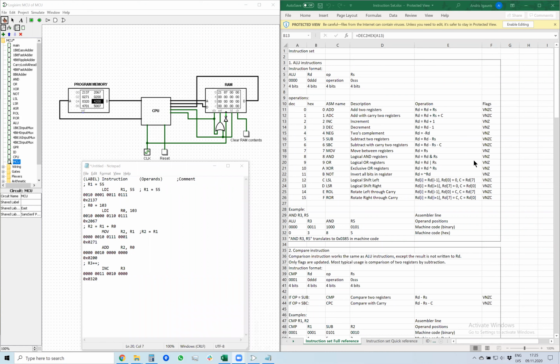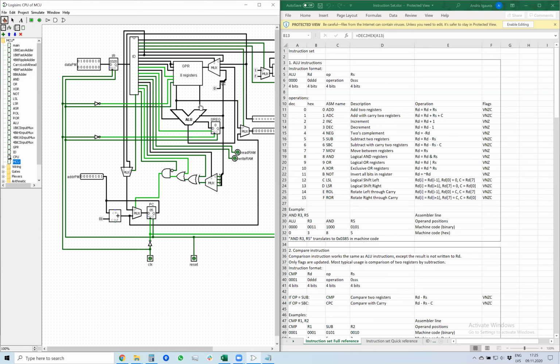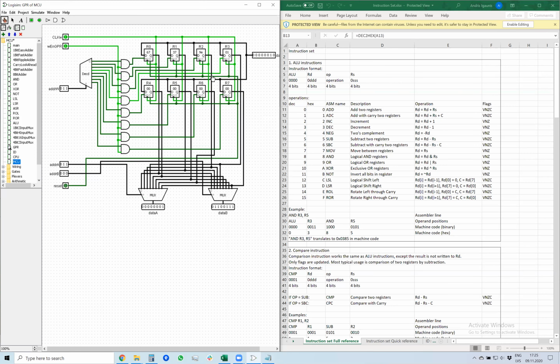Okay, somebody wrote something. The result for add for me is minus 98. The reason that your result was minus 98 is that as an unsigned number, if we imagine it's an 8-bit positive number, it's going to be 158. But if we imagine it is a signed number in 2's complement form, this is the same as minus 98.